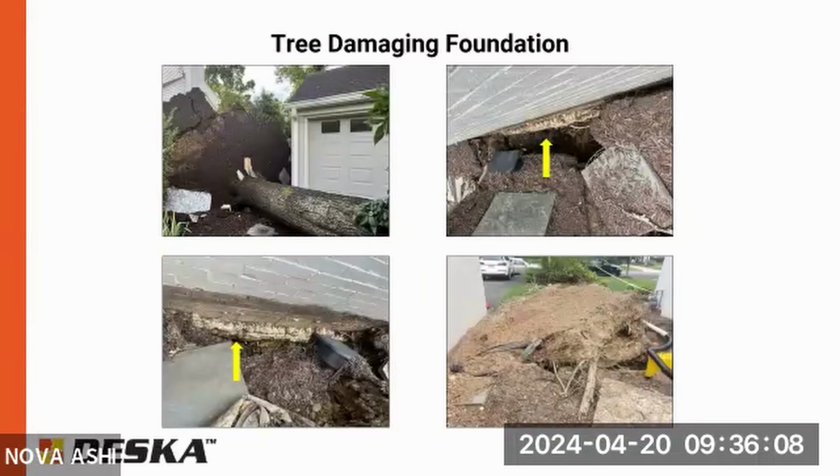As home inspectors, what we get taught for concrete slabs is concrete's gray, it's hard, and it cracks, right? And so we see cracked slabs a lot, especially in basements. At what point would you recommend to say, hey, this is something that we should pay closer attention to and need to refer to someone like yourself versus, yeah, this is the normal cracking we see? Typically, for myself, I do if there's a deflection between the height and the crack, or if it's significantly wide, right? What would you say to us as the inspectors? Like, okay, this is a point in which you need to refer to someone else.